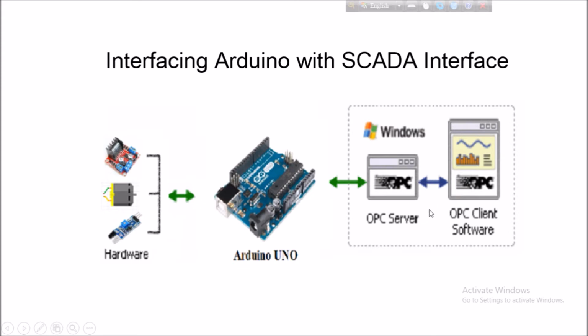Next, we have to create a SCADA interface in CX Supervisor software, and also we have to configure it properly so that this SCADA application can communicate with the Arduino OPC server.